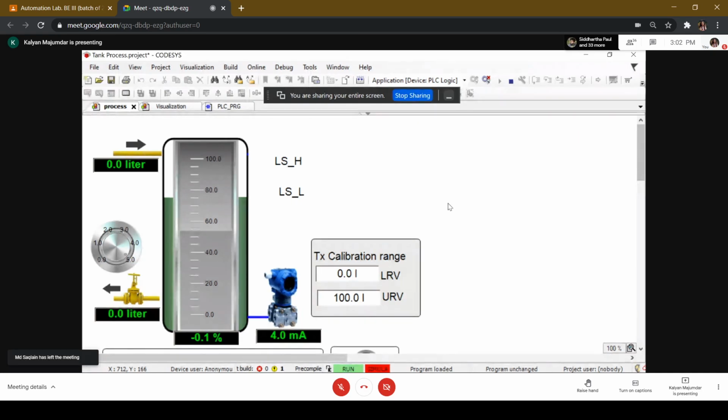Logically, your inflow rate should always be greater than the maximum expected outflow rate, so that even if you're consuming the maximum amount of water, when you turn the pump on the tank fills up and the level in the tank increases. So that is the first requirement. Logically, the inflow rate should be greater than the maximum outflow rate.